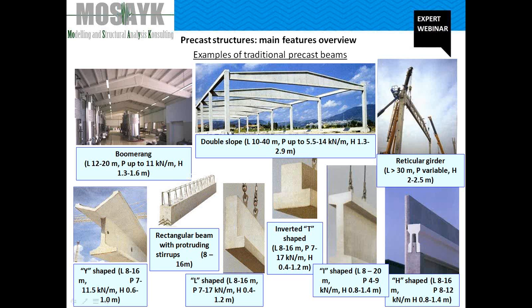At mid span, the height of the beam is a few meters above the top of the column. This means that the mass of the roof is moved up by many meters, and this will for sure change the period of vibration.